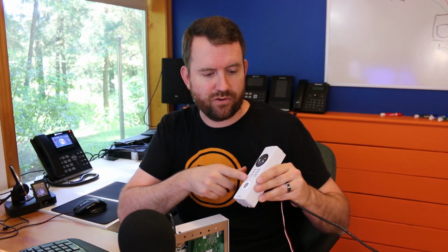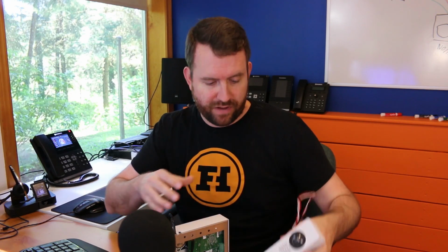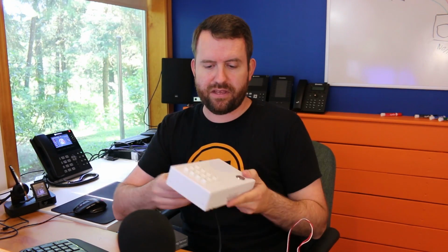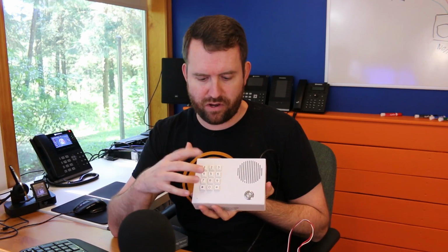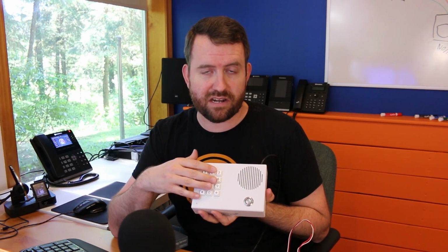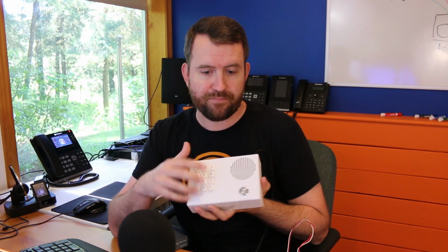There's a quick look at how to set up a relay to an electronic door strike. And this same concept works with all kinds of different devices. So of course, I was showing the Access Network Video Door Station. That's one type of device that you can use. You can also use something like similar products from CyberData, which have the keypads integrated where you can have predefined codes that unlock the relay as well as the button. CyberData also has video versions of this same device that can get you video as well.